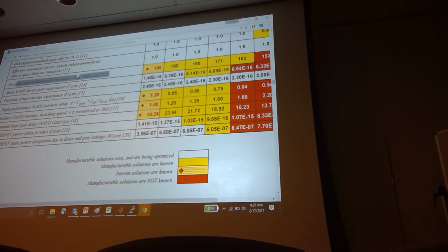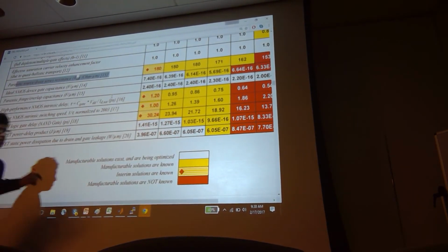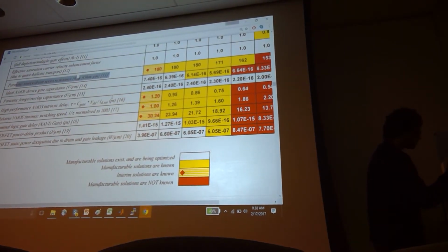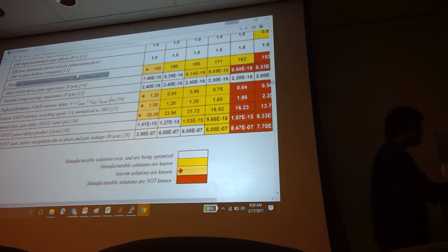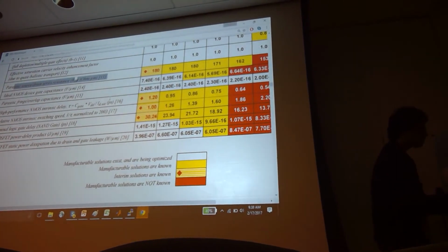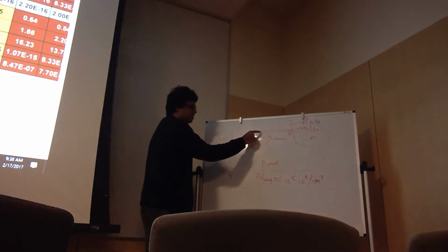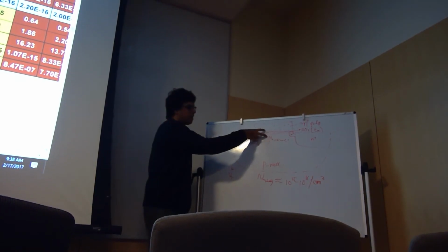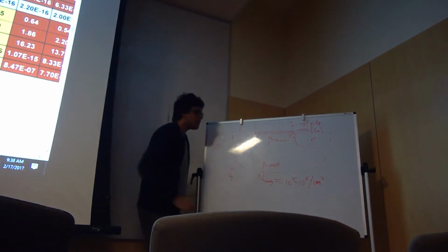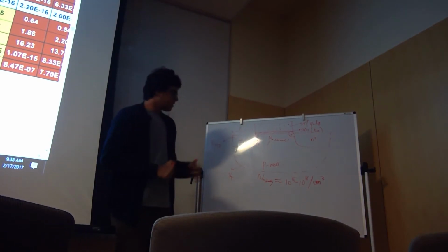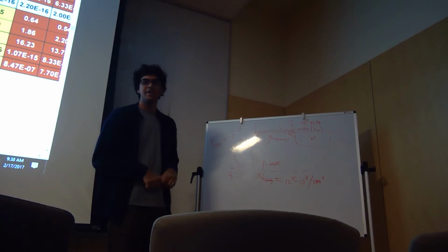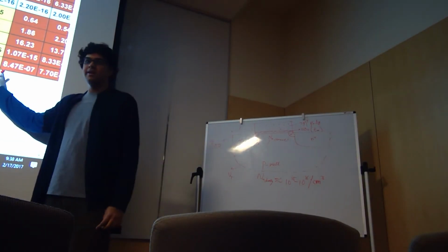So you can just go over this. In order to design this, you need RSD. You need to know what your parasitic source drain resistance is. In order to design this, you need to know what your threshold is. Again, you need to know both your threshold and what capacitance and gate control you need. So obviously you can figure out there are too many design parameters here and not enough equations to solve it. So that's the reason why I gave you this ITRS, okay?